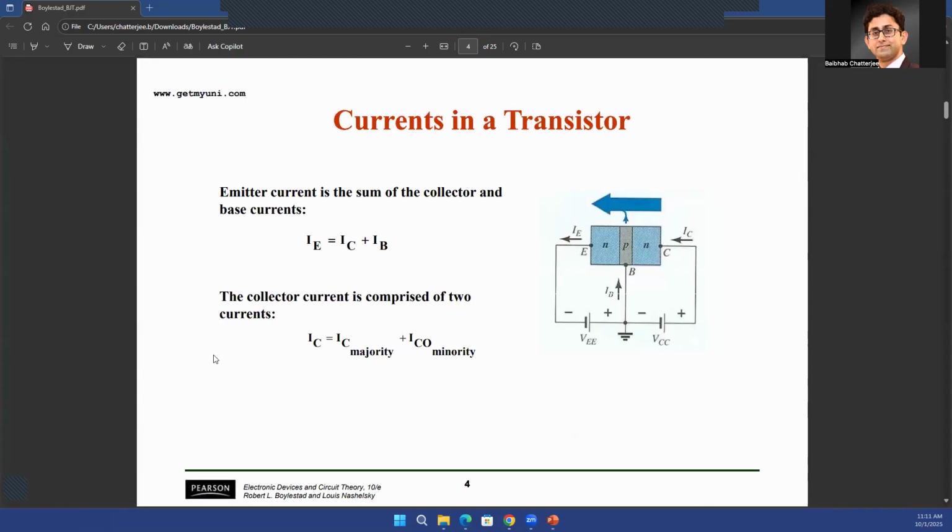All right. So what does that do? From the emitter, if you think about an NPN transistor now, the emitter is the source of majority carriers, which will be electrons. And the collector side would be the collector of majority carriers. Now, if you're forward biasing the emitter to base junction and reverse biasing the base to collector junction, what would happen in this case?